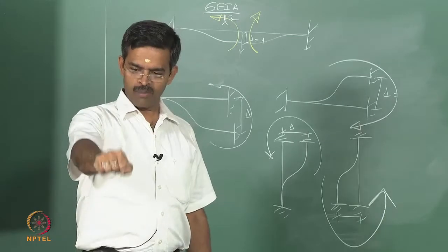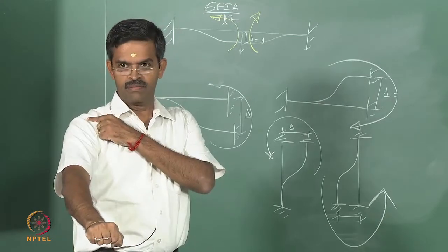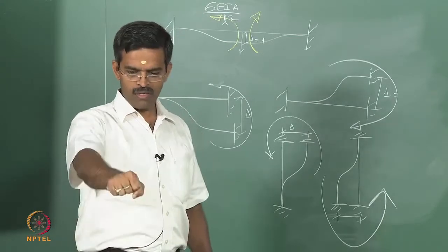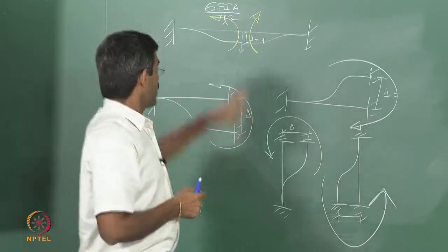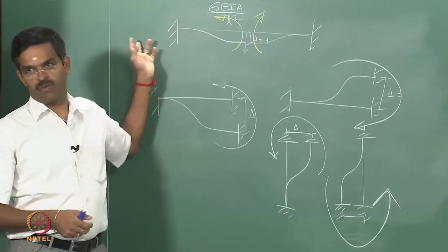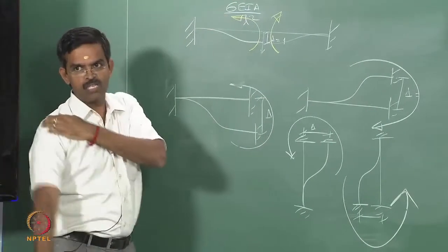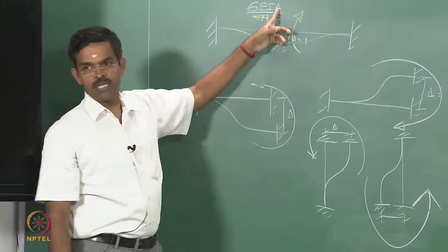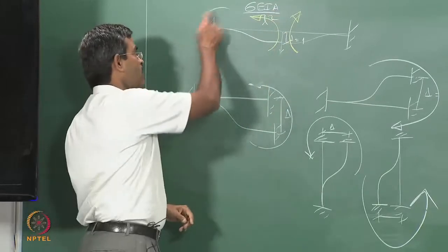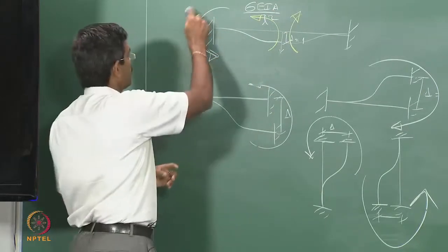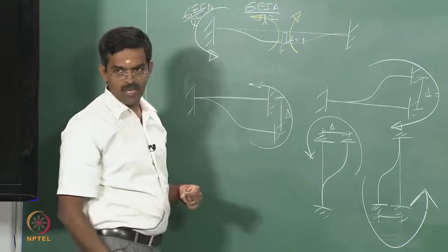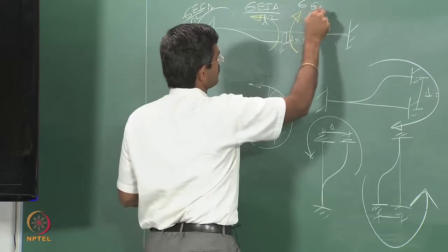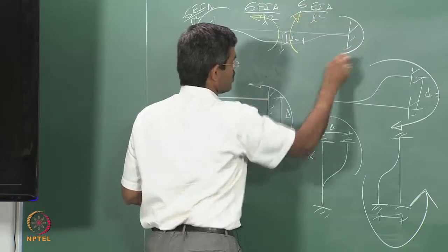The moment you give a displacement, you will feel a pain here. Lift a weight, you will not feel the weight here. The pain will come here actually. Right? It will try to move to the nearest support. So it will cause a moment actually, swinging is moment. So this moment is because of the deflection. Same effect will also go back here, which is 6 EI delta by L square. This is also 6 EI delta by L square.